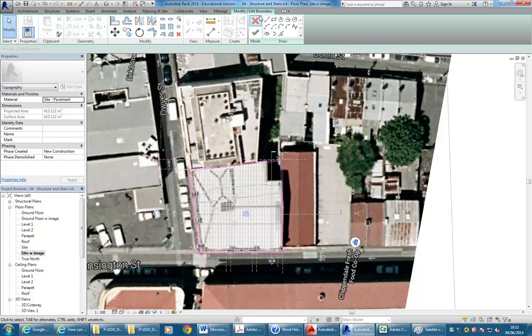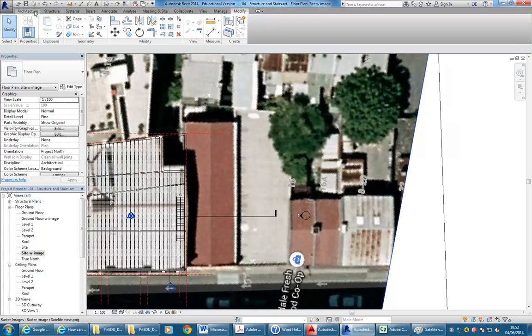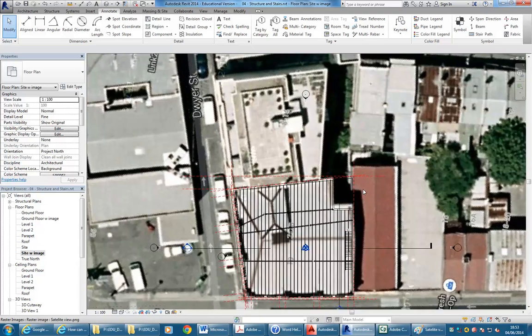Oh, so it's just frozen. There we go. Okay, so with those buildings there, you could just do something as simple as regions, or actually just hatching in AutoCAD. So you could do those over this site plan, and that would be good enough for the buildings in this drawing. But because you'll see them probably in other views, it's not a bad idea to have them shadowing in 3D the way it would in real life, and when you start looking out through your windows, you can tell whether or not you get a good view through there if you've got things around it modelled.